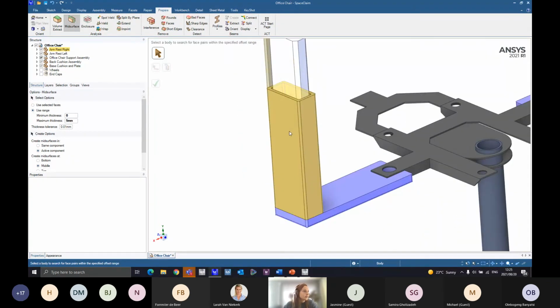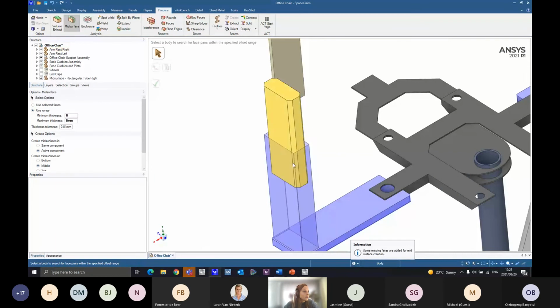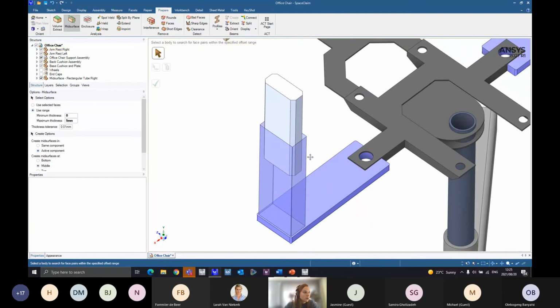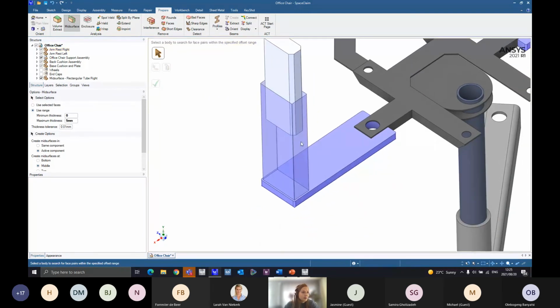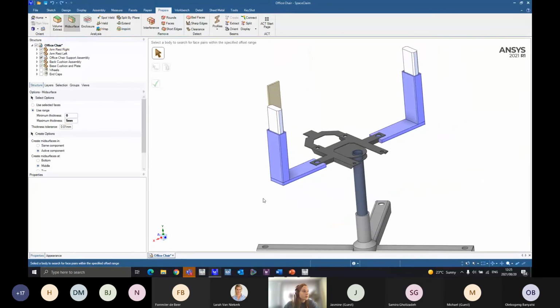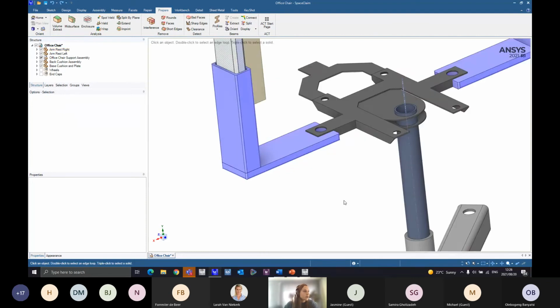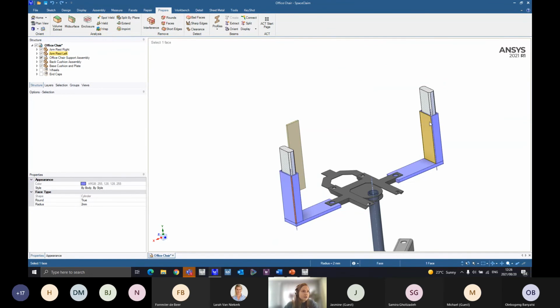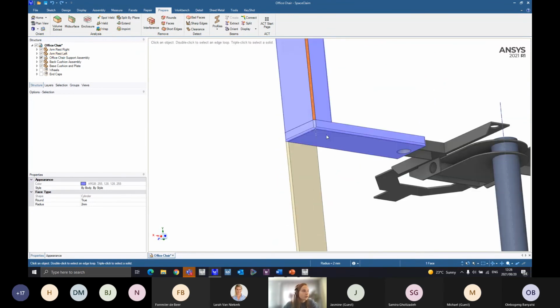So if I select this and I mid-surface it, you will see if I keep the rounds in, it still captures the curvature over there, which is not really something I want when I want to mesh my geometry. So I'm just going to undo that and first maybe remove the rounds. To do that, I think it would be best to use some of my power selection tools. So I'm going to select this round. I want to actually remove all the rounds on these